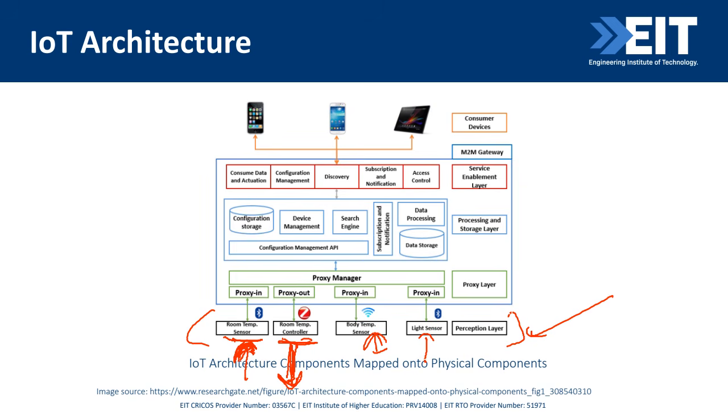It could be occupancy sensors. For example, you can put sensors to detect if someone is in the room. You can use infrared sensors that will allow you to know if someone gets into the room or out of the room, so you can start counting how many people you have in the room. So these are the kinds of sensors we can add quite easily in our applications.